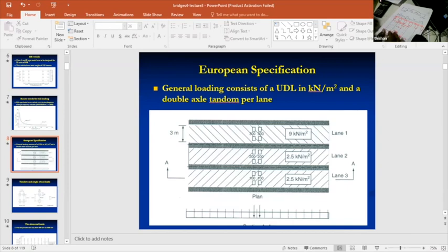So you can actually apply 9 over the full width and just consider it as it is. We'll apply 9 kilonewtons per meter over the full width, because those are the locations where the beams are coinciding. So when you apply all these loads on the transverse members, what will happen?